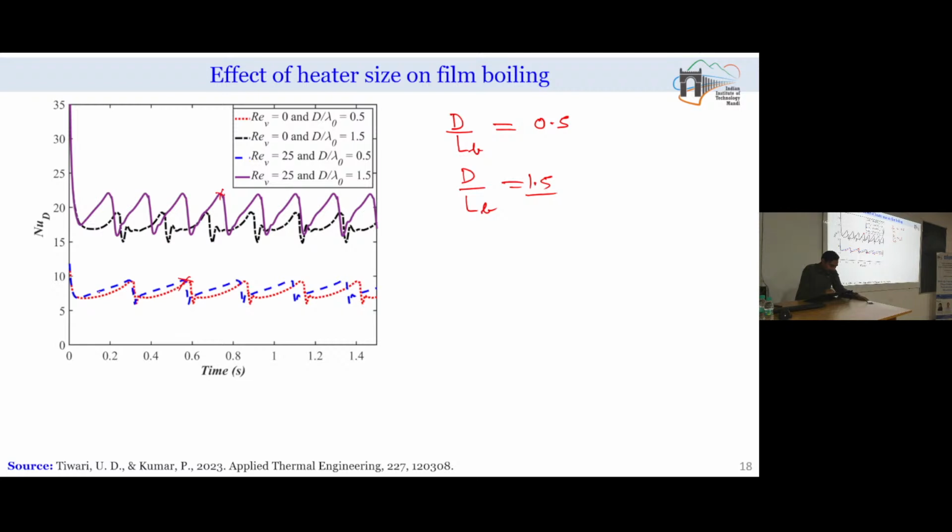We do have cyclic behavior there also, but the minima and maxima in heat flux are less in comparison to the minima and maxima obtained for the larger cylindrical surface. Another interesting feature: because we are not changing the fluid combination, the vapor volume will almost depart at the same diameter.